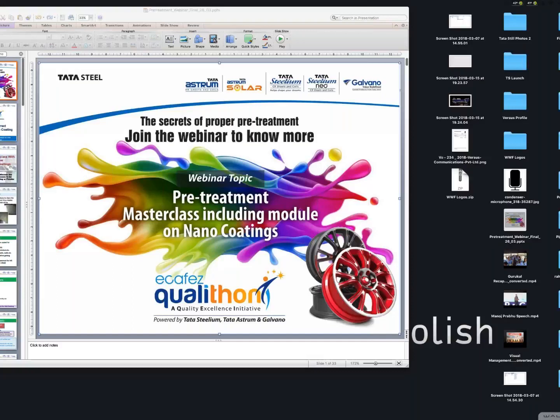So please ensure that your earlier process does not use any mustard oil for deep draw or this kind of operations. Secondly, nowadays there are certain oils available in the market which we call water miscible oils. Even they are available for deep draw pressings. If you use these kinds of oils, there will be a lesser load on your degreasing tanks.